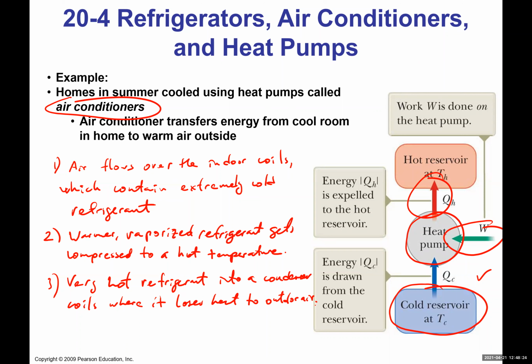And the last step, let's call it step 4, is that this refrigerant from outdoors is moved inside to the inside unit, and then it basically cools down. It has to cool down again, so that the cycle can repeat, right? Because if you send that warm, still relatively warm air into the inside unit, you can actually add some heat into your house rather than remove it.